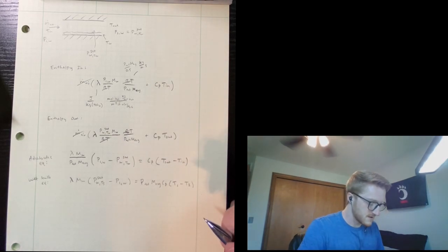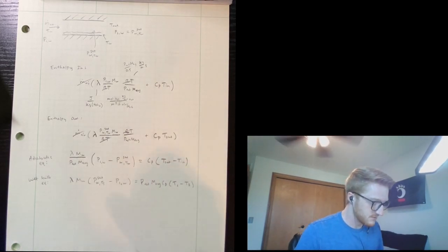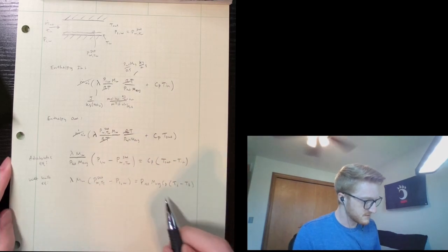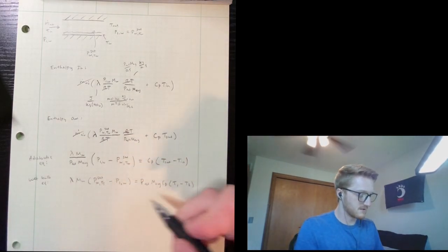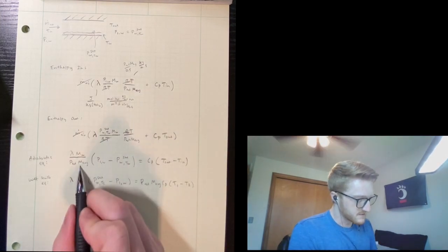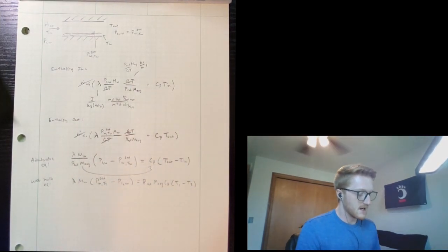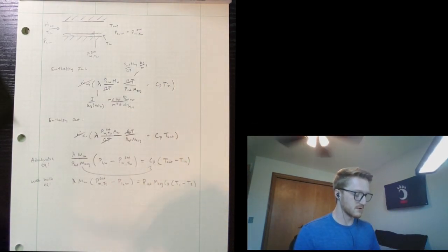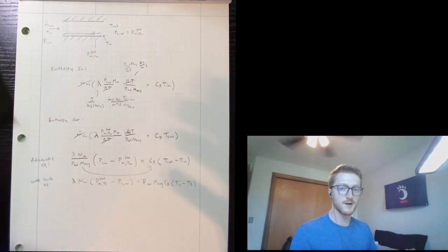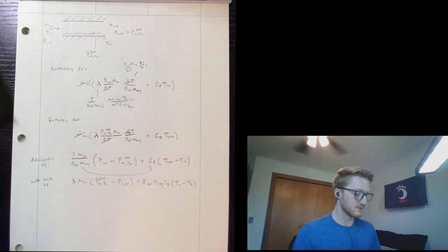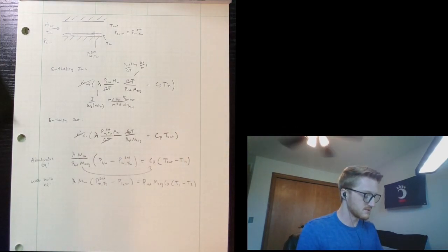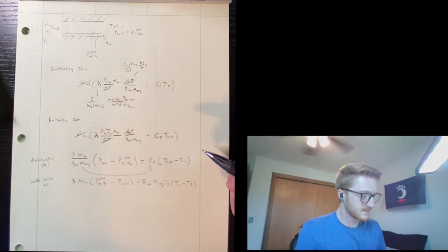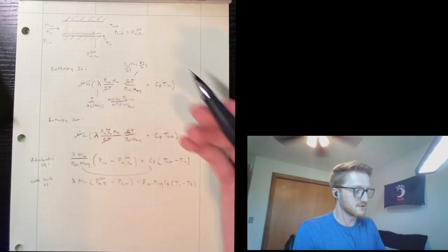And if we finagle this around a little bit, we can see that they're exactly equal. You would just multiply the negative sign throughout, move this over here, get this, and you'd have the same thing. And so what this allows us to do is to know that what connects the two is that the temperature reading of the wet bulb is actually going to be exactly equal to the adiabatic saturation temperature. And so that kind of wraps everything up between the wet bulb experiment and the adiabatic saturation temperature experiment.